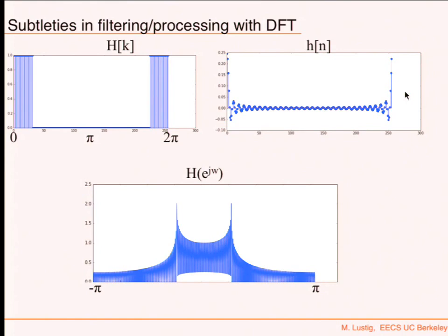Would it be smoother because h of n is not periodic, or is it periodic? h of n should not be periodic, but if it was centered, then it would have been a smooth type of function that decays at the end, which doesn't have large variations. So the DTFT of it would have been closer to that. As opposed to here, where I evaluate those at the right places, but in between it goes crazy, because of this huge discontinuity.